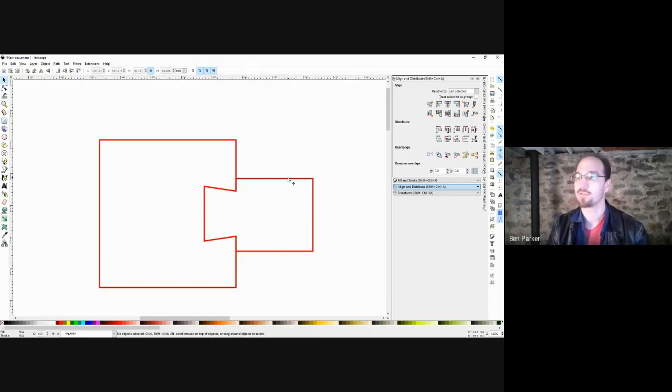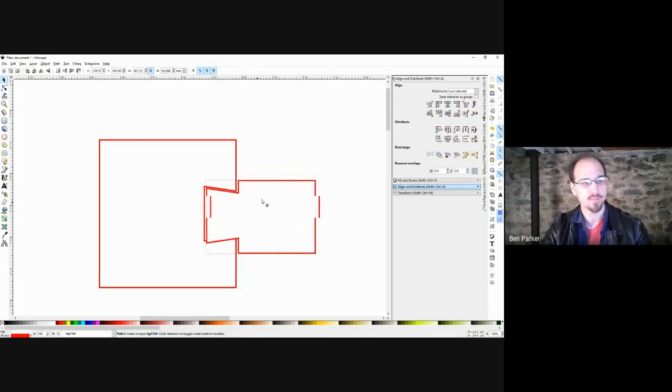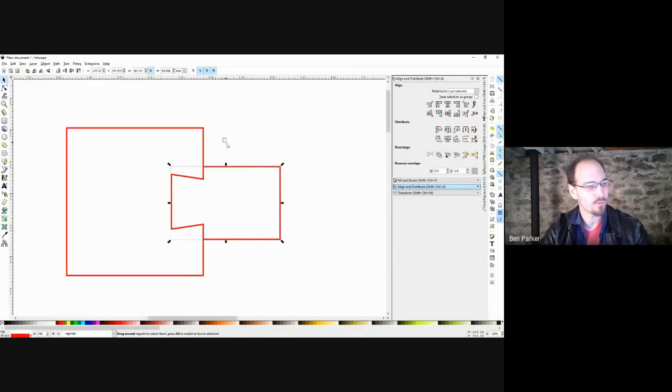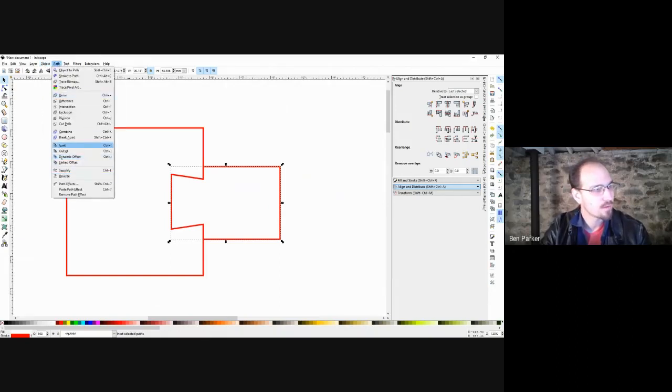Here's a cool thing. If you're trying to get fixtures inside of one another, like the kerf of the laser might not be enough. Like this might be too snug of a fit. One thing you can do, there's a couple things. I can click this and click here it is, inset.